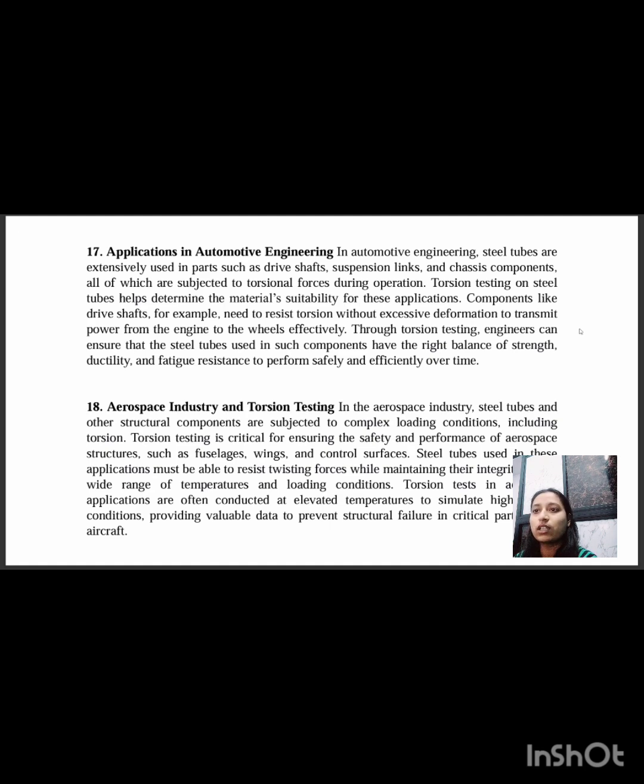Steel tubes used in this application must be able to resist twisting force while maintaining integrity over a wide range of temperatures and loading conditions. Torsion tests in aerospace applications are often conducted at elevated temperatures to simulate high altitude conditions, providing valuable data to prevent structural failure in critical parts of aircraft.